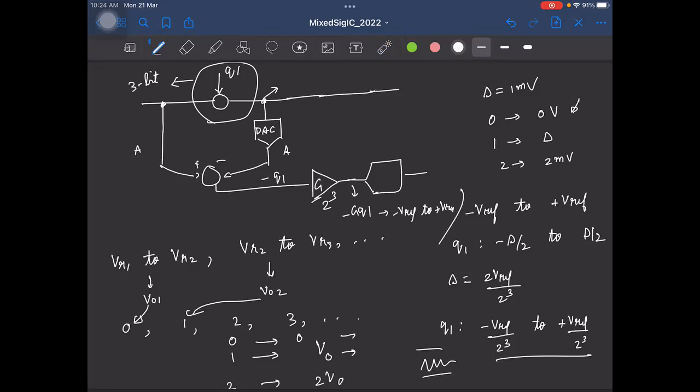So now I have the output of the first ADC. I'll call it V1, right? This is the first ADC, and this output is say U plus Q1. This is my ADC2, so let's say it adds a quantization noise Q2. What will be the output here? V2, which is minus G times Q1, the input, plus Q2. Fine. So let me erase this portion.